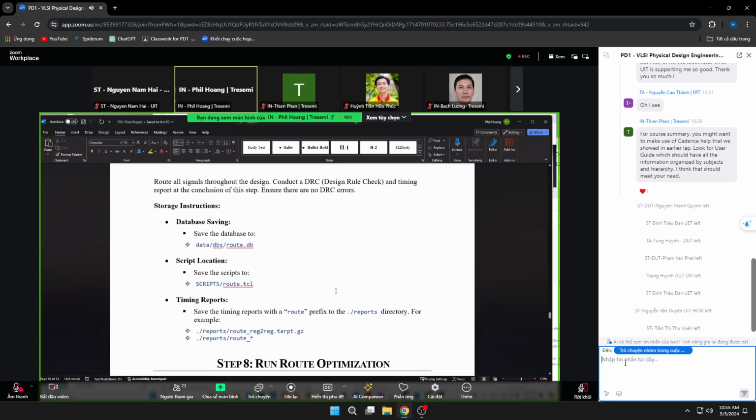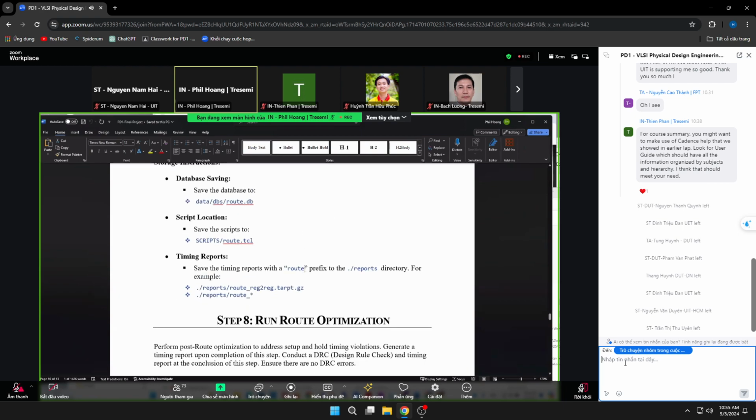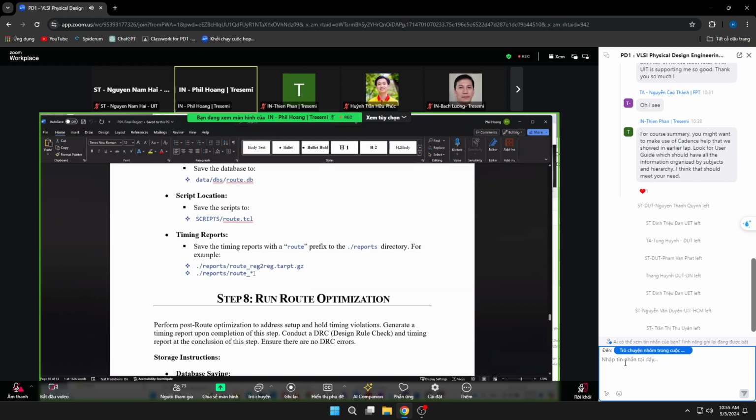So for route design, first you run route, making sure everything is clean. At each step you already analyze your congestion and so on, to make sure that by this time when you run a route, you have a clean route. And even though you do a timing report here, expect the timing to be messed up, because during this time it does very minimal timing fixes.